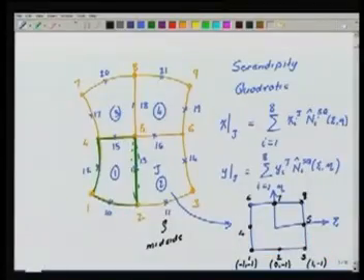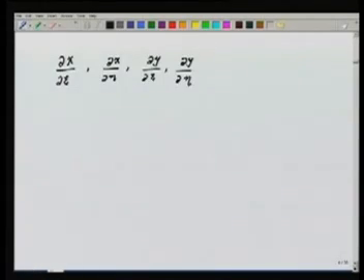Okay, so we compute these from the expressions for x and y in terms of psi, eta, that is, in terms of the shape functions that have been used to represent the geometry. Okay, and once we have that, we can obtain these expressions as functions of psi, eta, and we are in business. So we can find the Jacobian, we can do everything else that we need. Okay, so this is how we are going to handle a curved geometry.